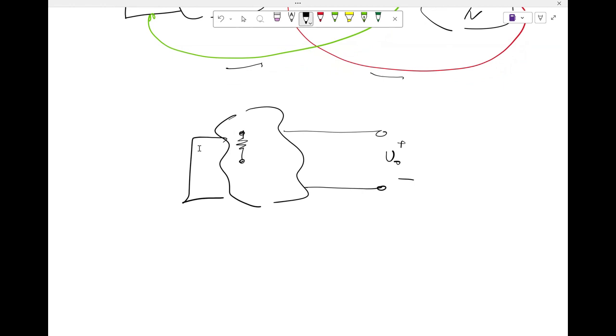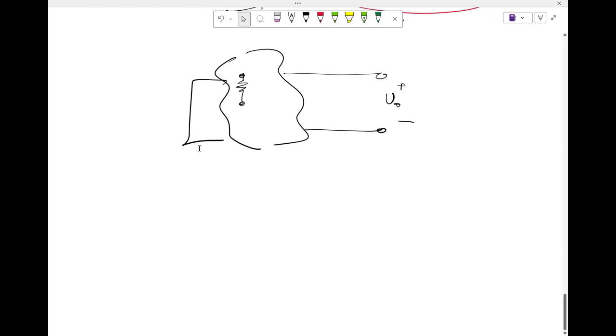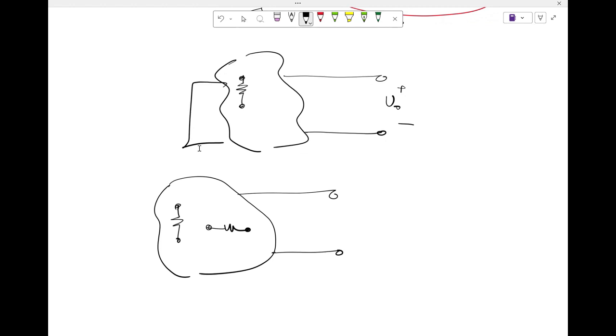I probably have missed one step, because before I go there I have to join some dots. I'm taking a step back, I forgot to talk about this. Let's say I have a network. I have two resistors here. They are not necessarily connected in any particular manner, but they are part of a network. Each of these resistors has a noise. I can model them as a noise source in series with them.